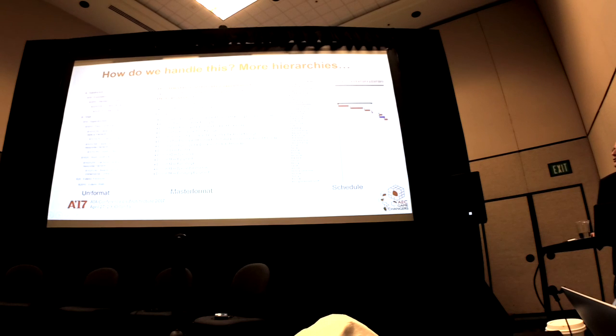So if I just look at a simple thing like the uniformat numbering system, it's got this numbering convention that is hierarchical. It's not a random number. The B20s encapsulate all sorts of exterior enclosure, and then there are sub-flavors of that, exterior walls, etc. So even though we're just talking about one piece of information, we can start thinking of that as a way of dividing and conquering that specific view of the world.